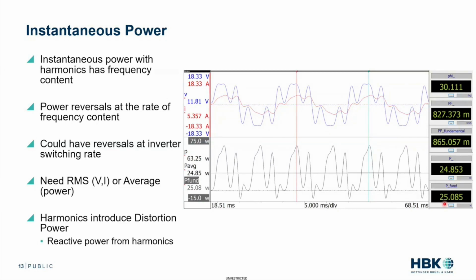So this is another circumstance where people will tell us, we get a different power value with your instrument versus somebody else's. Well, if you're filtering out the fifth harmonic in one instrument but not the other, you will see different power values. Even if it's just a little bit, there will be a difference, because which frequency band are you looking at? And again, I'm not going through math.